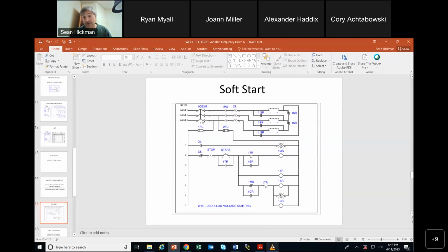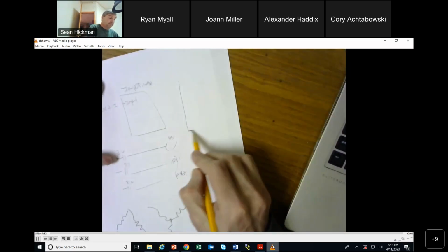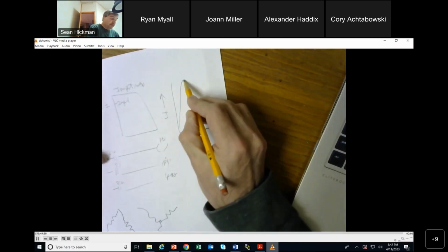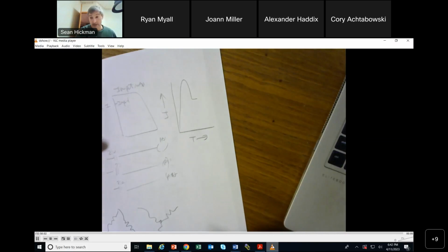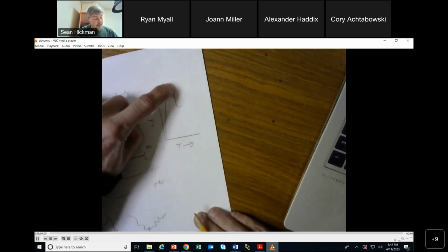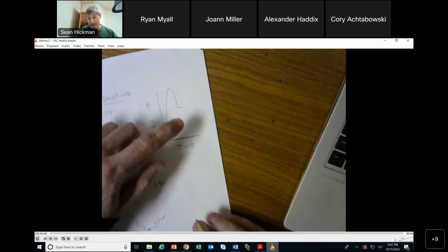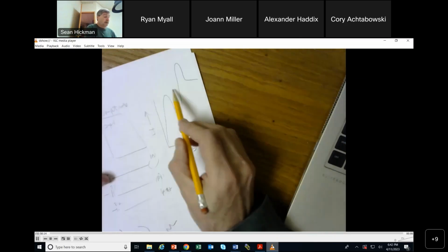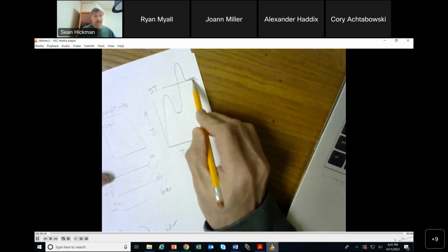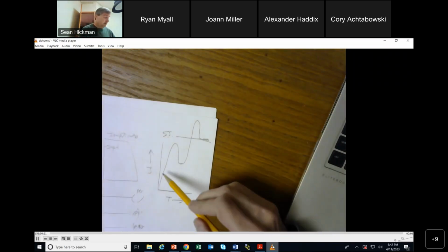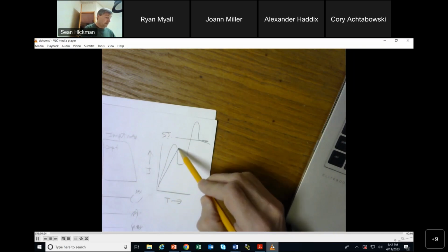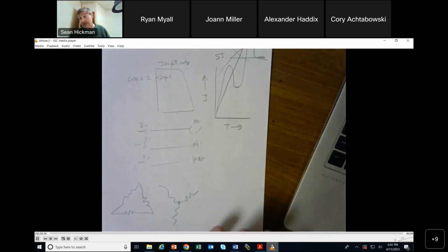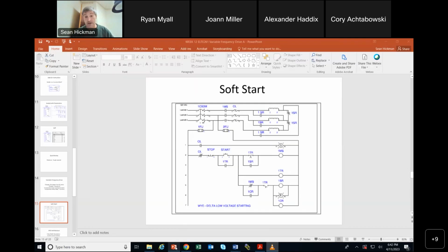And the purpose is to watch the ampacity that's driven, because we've talked about when we start and we have inrush current, where we have time and we have current, we get a spike coming up here. And then when it starts coming steady state, it starts leveling off. And so we might start it on the Y and get it running up to speed a little bit. And then we might switch it over and hit it up again like this with a delta. And then we might end up with our steady state current up here. Versus if we would have hit this right away just with a delta like this, it might have just popped the circuit breaker completely. The inrush might have just been too much. So that's called a soft start.